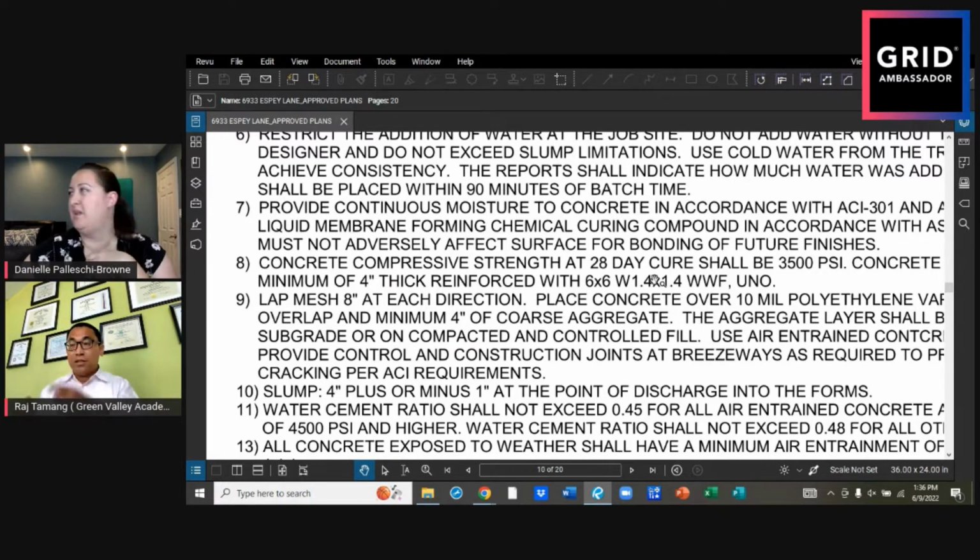Wow, that's amazing. The longer it goes, it's a longer process. Sometimes it takes 1 year, 2 years to continue getting that strength. But like I said, that's very negligible. So the strength gaining process is quicker at the beginning, but as you go past more days, the process is slow. That's why when you pour the concrete, you can't start using the concrete slab or footing immediately, because you have to let it cure for a few days.